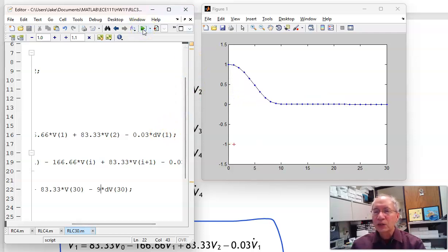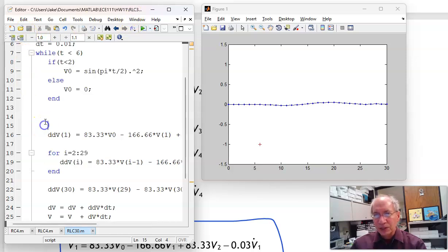When you take electromagnetics, you'll calculate what that number is. For now, using MATLAB, I can use trial and error and tune it to try to get rid of the reflection. This says that 1 over RC on the last node should be 9. So going back to the standing waves, let's run it for 20 seconds and see what happens if I make the last node 9.